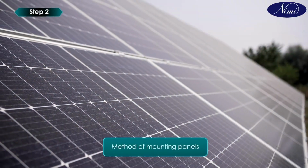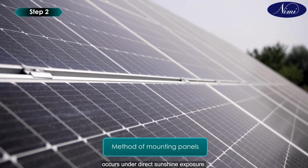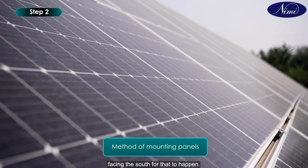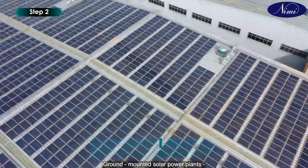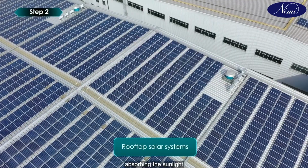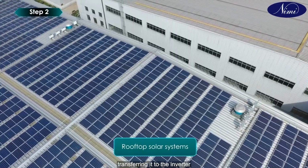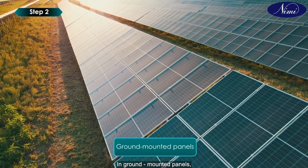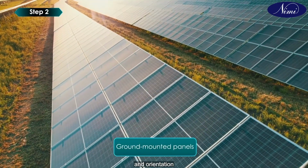Method of mounting panels. The best solar panel performance occurs under direct sunshine exposure. Modules are positioned at an angle facing the south for that to happen. Ground-mounted solar power plants function similarly to rooftop solar systems. This includes absorbing the sunlight to generate an electric charge and then transferring it to the inverter through conductive wires. In ground-mounted panels, the structure is carefully selected with a tilt angle and orientation to maximize sunlight exposure.